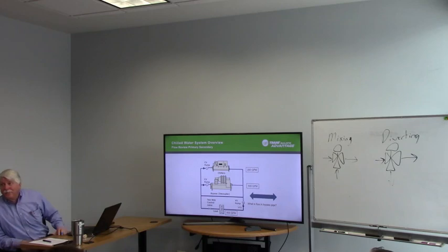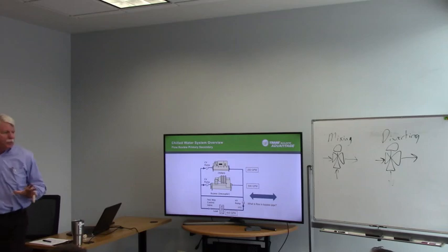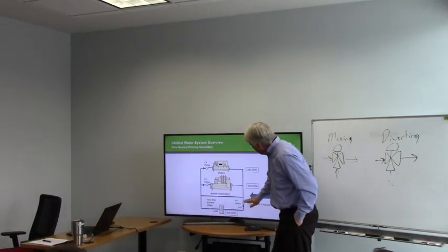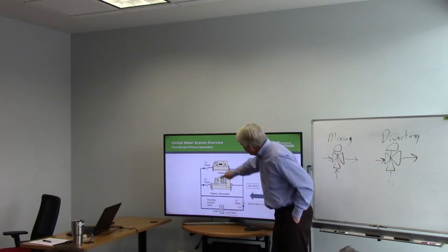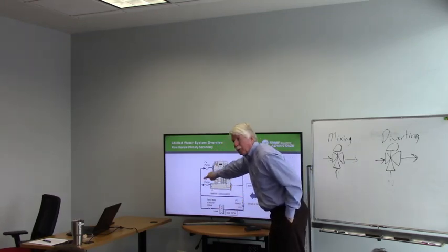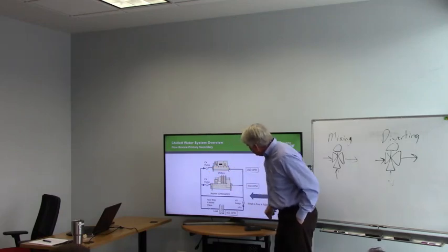Okay, now, the pump down on the bottom is now moving 600 GPM. Now does everybody see that we have 2 loops going here that are completely independent? Regardless of what is going on down here, this pump always has a path to get water, so it can move as much water as it needs.